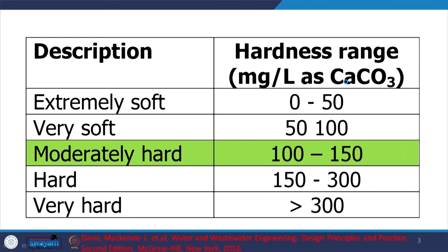So let us see what else we are going to look at. What class is it when we consider the water as hard? When the water is 100 to 150 milligram per liter, that is when we are concerned with hardness, right. And in general, in Roorkee, we looked at the relevant values, it was 250 or so. So it is typically hard, with deposits upstream. Above Haridwar, upstream of Haridwar compared to the flow of the Ganga canal, the water can be extremely hard. So hardness again is an issue at most places, and in the south, depending upon where you are, the hardness is remarkably high, right.